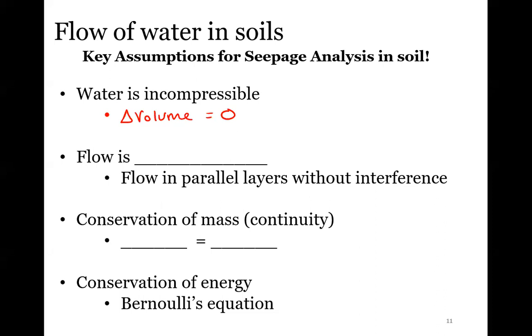And if you remember the Poisson's ratio, that means the water has a Poisson's ratio of 0.5. So any deformation in the vertical direction is going to have an equal and opposite deformation in the lateral direction. So we're squeezing this way, it's going out the other way.